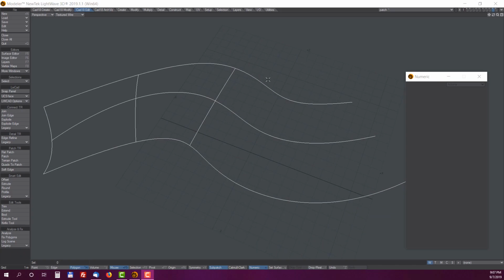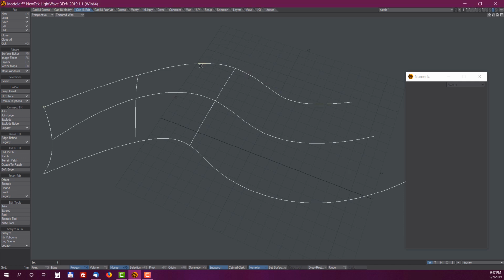Finally, network patching. This is the most complicated, and all these railing curves along U and along V must each be a single segment, not divided, and each crossing between these railing curves must be touching. These railing curves must touch in these points.